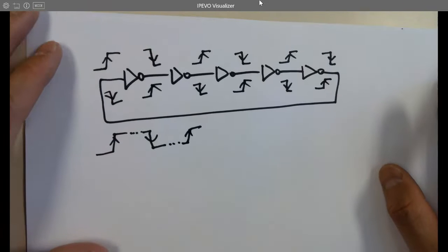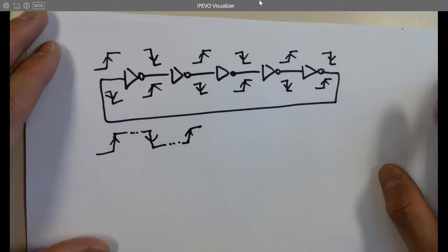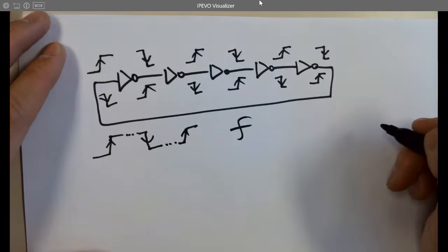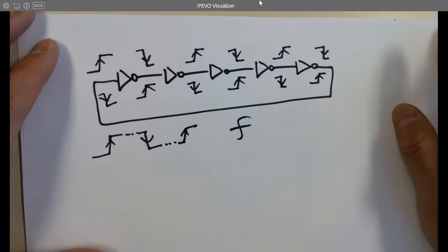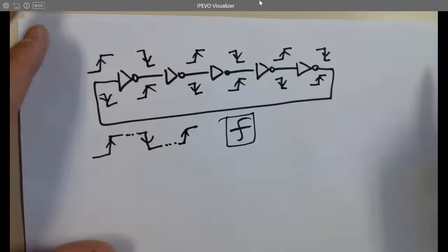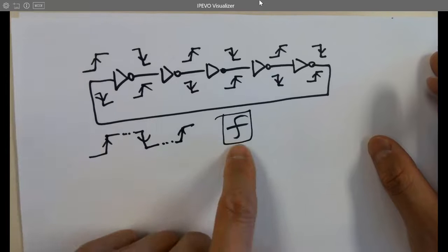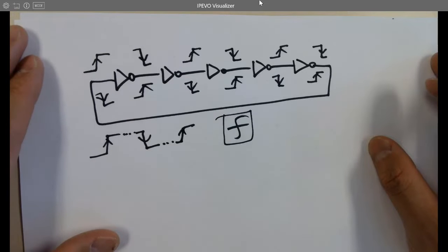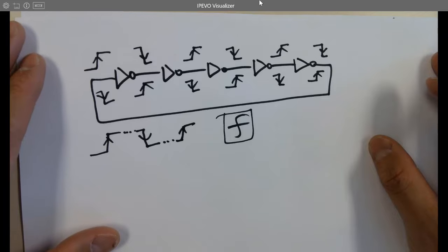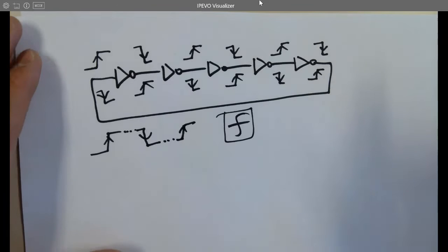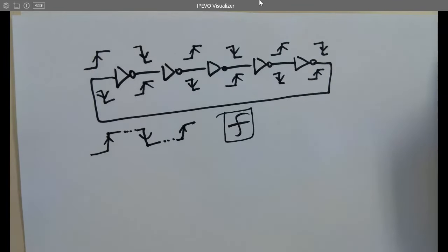So how to calculate the time delay, which is, if you know the time delay, you can calculate what? The frequency of the ring oscillator. Why is that important? If you are trying to design an oscillator for an integrated circuit, you want to know the frequency, so you know the clock frequency. Internally, sometimes we use a ring oscillator to generate a clock, but not the main clock from the crystal for microcontrollers. That's the main clock from the outside circuit. You just solder that thing to the board and power it up, it's going to oscillate.